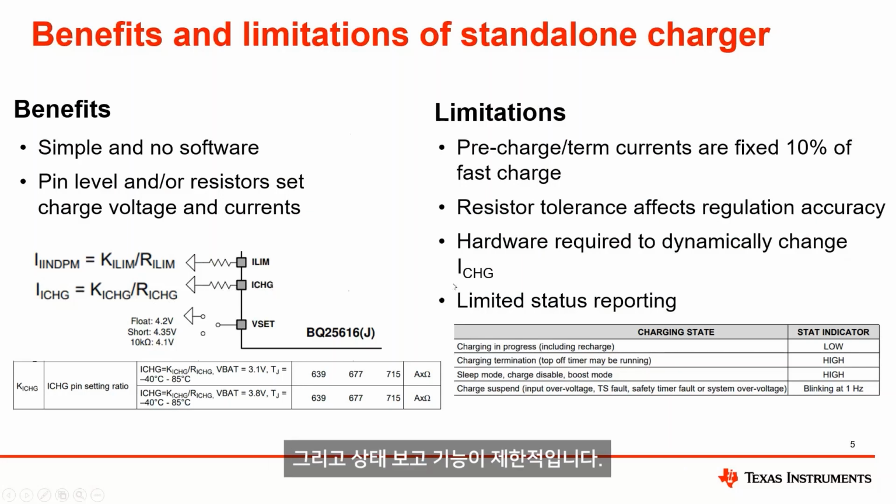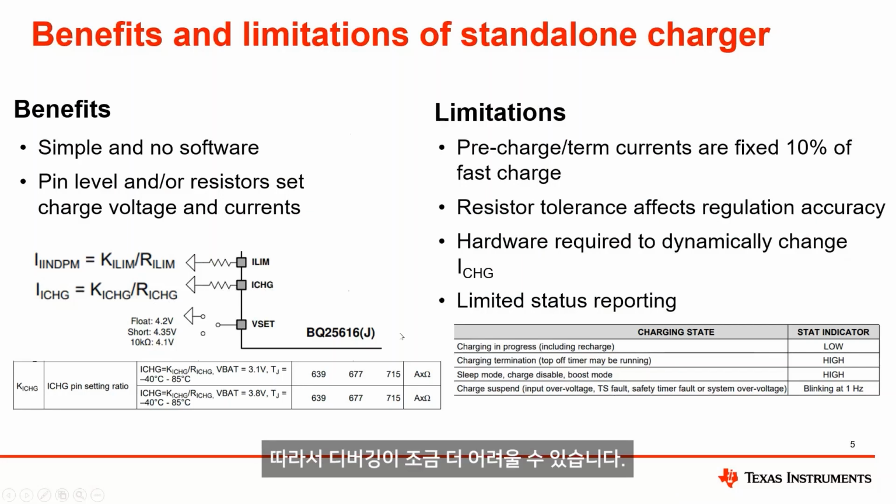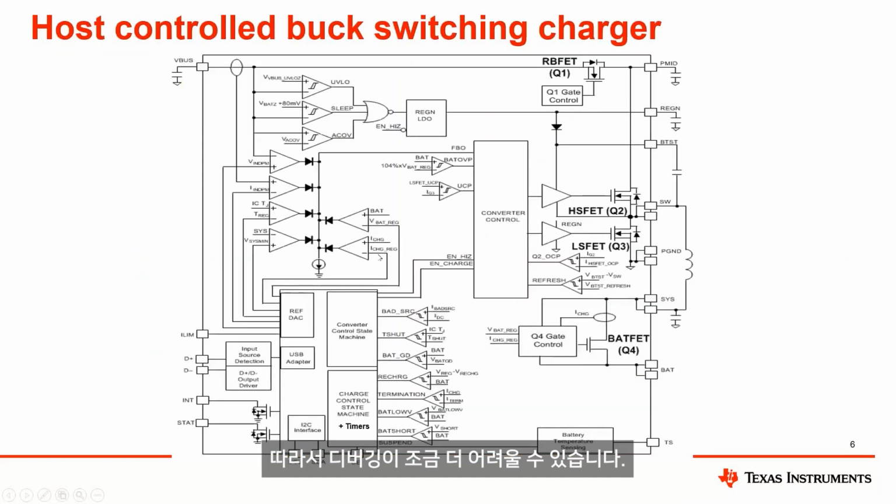And you do have limited status reporting. If you've only got one STAT pin, it's either low or high or potentially blinking to let you know that there's a fault, but a blinking would indicate numerous different faults, so it might be a little bit more difficult to debug.